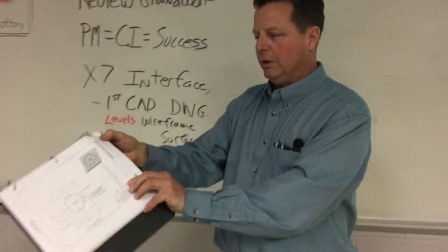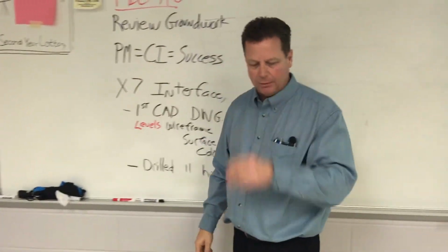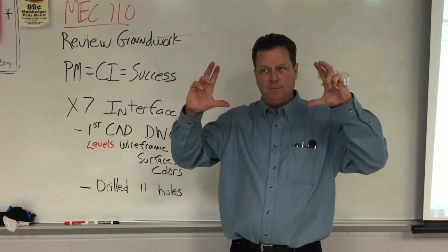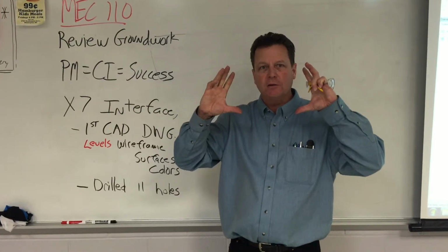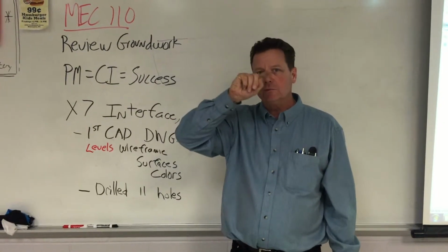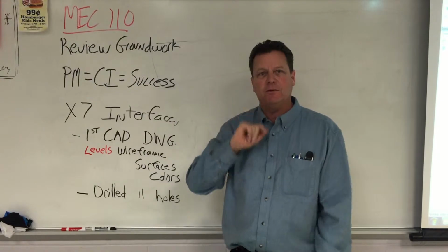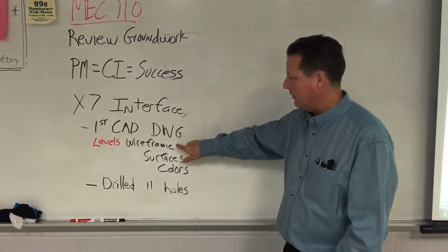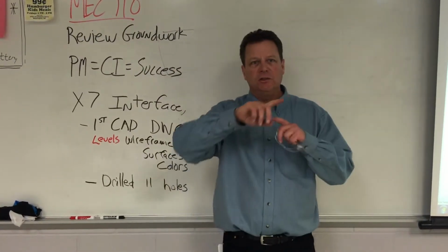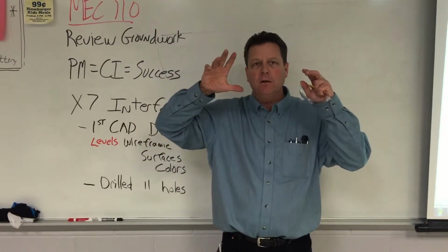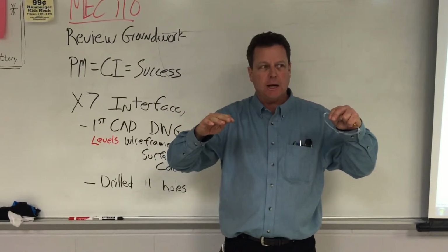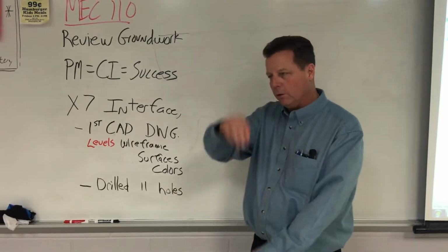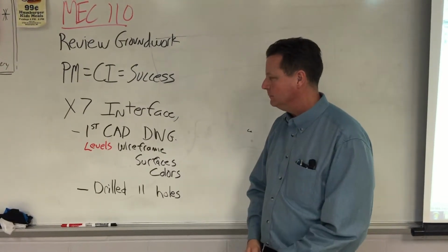All right. We drew this simple plate with a bolt circle in Mastercam with a line, the anchored to center rectangle tool, and then we said create bolt circle, and very quickly we had the 2D geometry. Then I showed everybody how to translate that down into wireframe. We clicked and got everything yellow, and then we joined the geometry down 1/4 of an inch to get the wireframe that we wanted, the holes all joined down that way too.